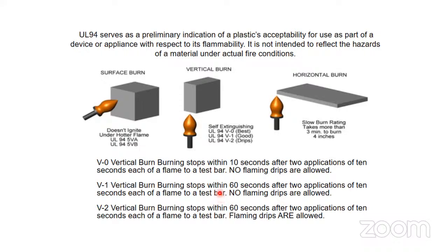But if your thermoset material is presented in a coating form, thermosets are generally used for coating purposes, correct? So if your thermoset material is coated on some surface, like suppose you have a block and you have coated your thermoset material on it, then that coating you can't burn using the vertical burning test. In that case, you can apply the flame on the surface of that coating, and after that burning you can take the readings accordingly.